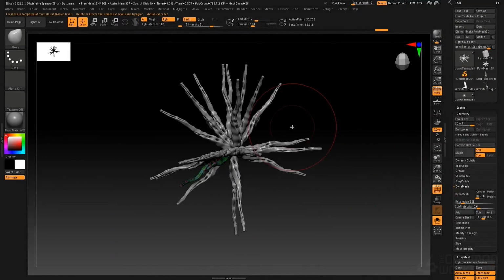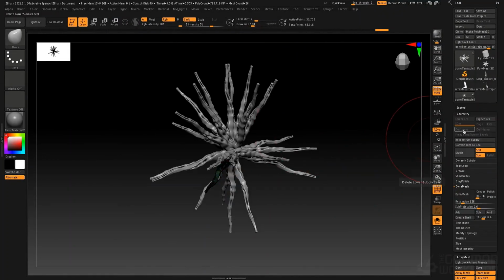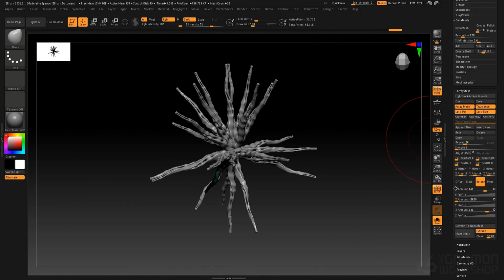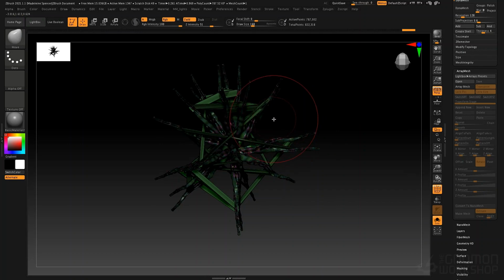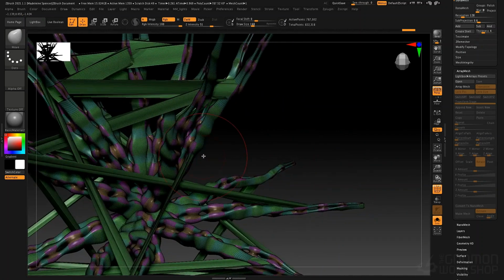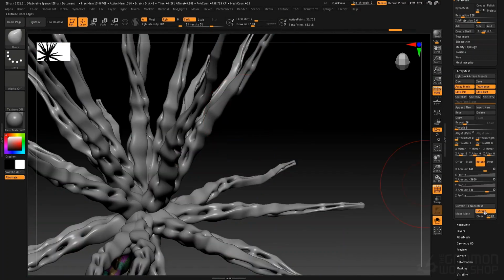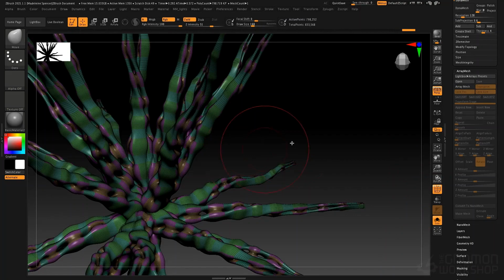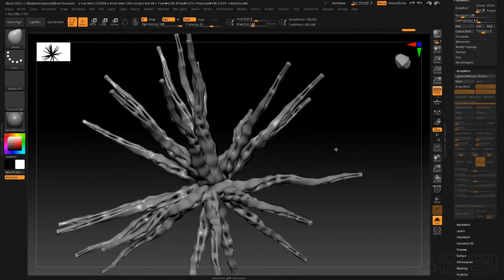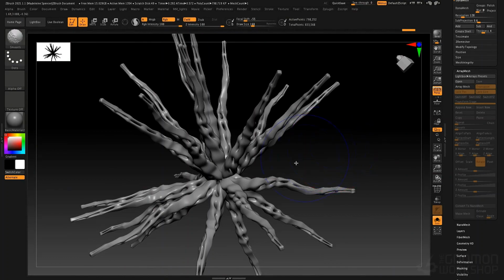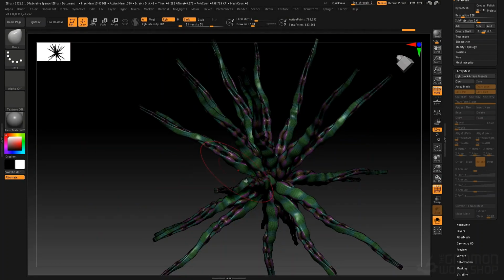I have 4 subdivision levels that I just added to this, so what I need to do is delete those subdivision levels and then make mesh, and that will generate actual geometry based on that. But see what's happening is it's trying to connect all of those polygroups again. So I need to undo, make sure extrude is turned off, then I will successfully be able to make this into a mesh.